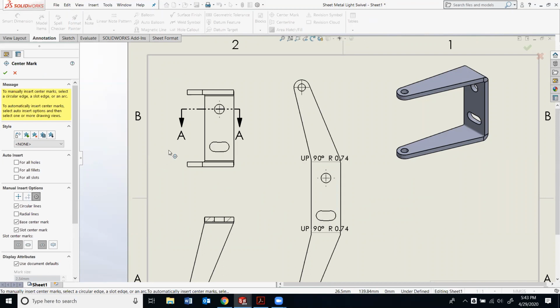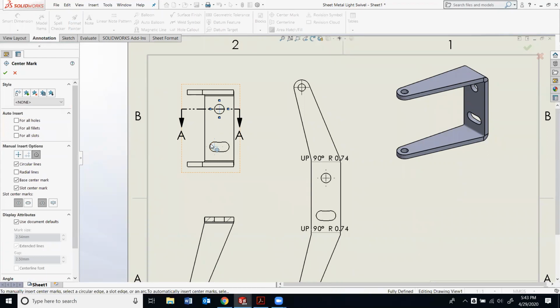And what you're going to do, and you have to do this very precisely, you have to click on this circle, the top one first. So click, and then click on the 2 on the bottom. Click on this one here, click. And then when you click on this one here, it actually curves them so that they point towards this one here. Okay, again, that was this rounded option here. And hit OK.